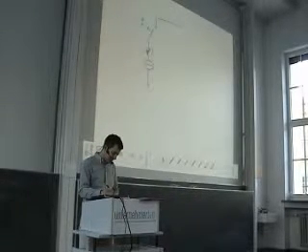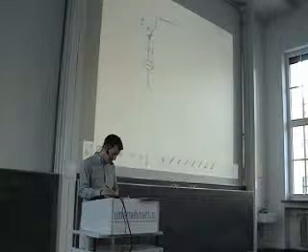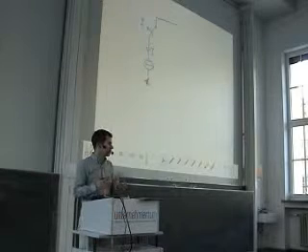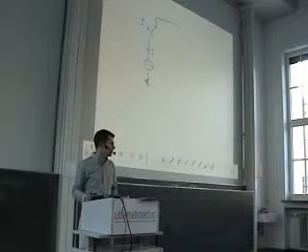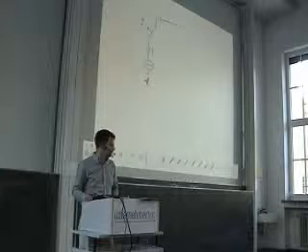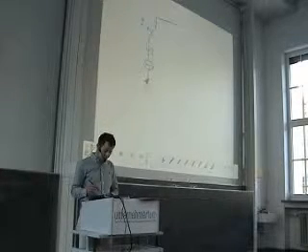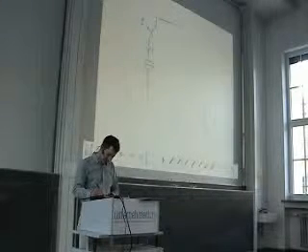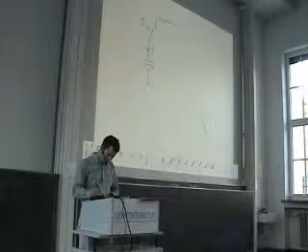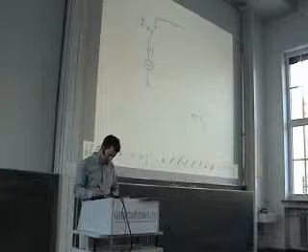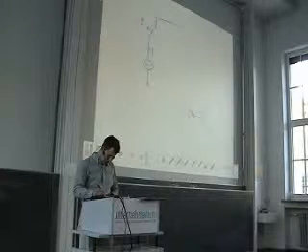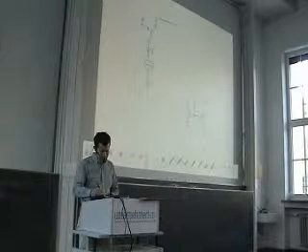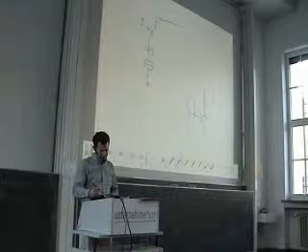Otherwise, again, if I disconnect it here only and connect it to nothing, the current source wants to sink this current, we have an over-idealized situation, which is not possible. So let's look at a real current source. A real current source is in the most basic case a transistor. For instance, something like this. Okay, here we have a current mirror. This is our current source here.